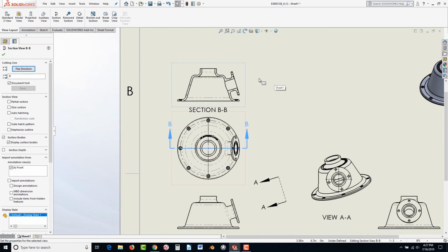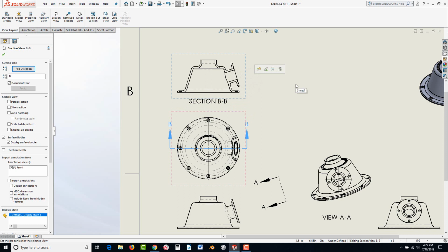Now, again, SolidWorks sticks with the ANSI standard when you select ANSI standard, and some shops that I've worked in really preferred to have this more of an unfolded view as though it was upside down. You have the option with this little arrow line here, just double click on it, or you could flip the direction button. Either one will reverse the arrowheads, but now you might not see this update. Instead, you might get this strange cross-hatching.